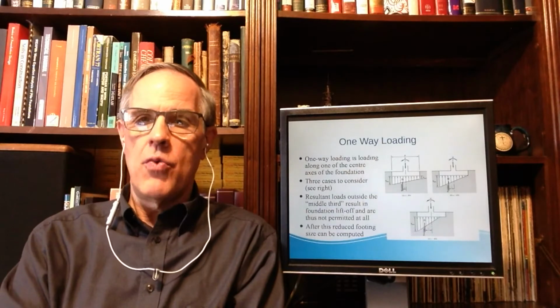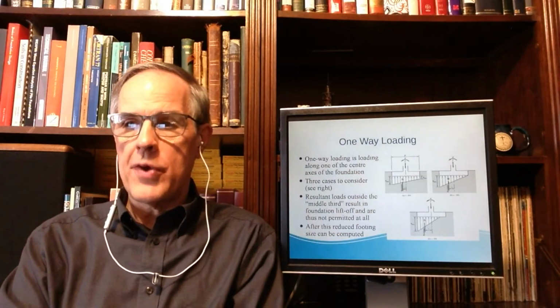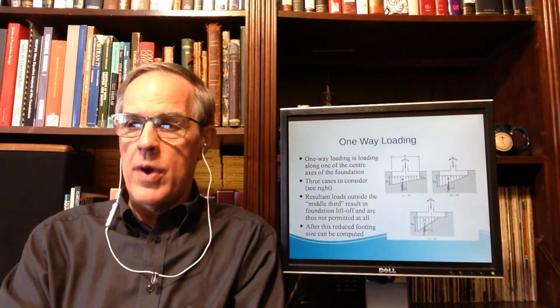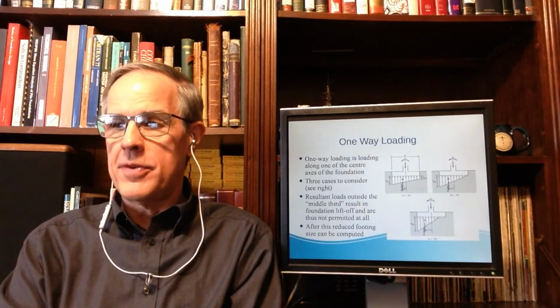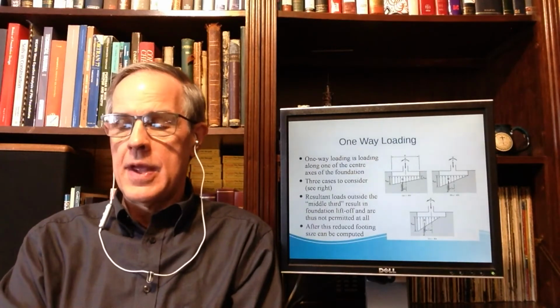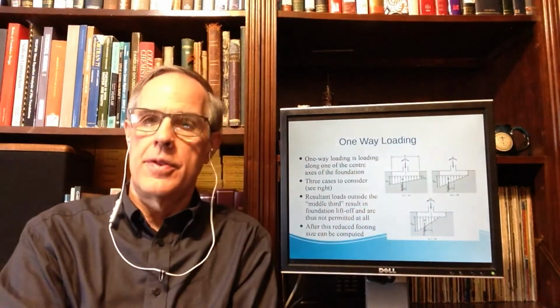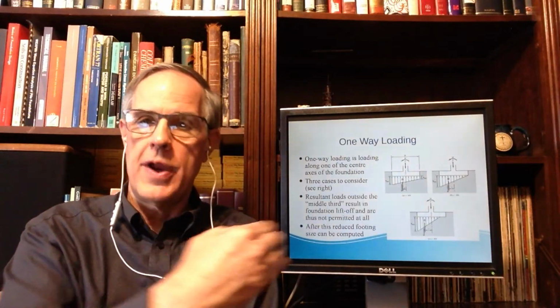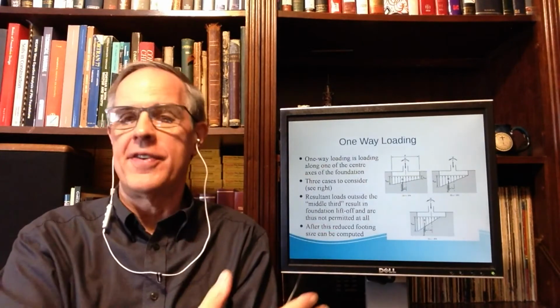We say that once you move off the centroid with the load, it ramps. Well, if we run the statics of this, what we end up with is something like this. If you start moving it from the center, you get this result. It starts to be a ramp load, but there's still pressure across the foundation.